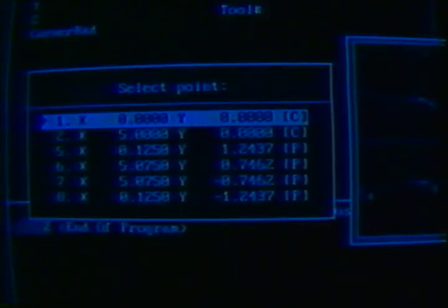If I want to do a line to the next intersection, I would repeat the process. This time I would select Line, Recall from the geometry calculator, select point number 6, and choose X and Y. The XY coordinates of point 6 are input directly into the CNC program. I can continue to recall from the geometry calculator at any time and input all necessary XY coordinates until my part program is completed. Values can be recalled from any one of the three calculators.